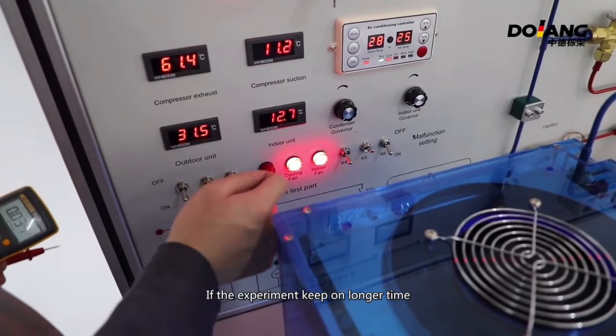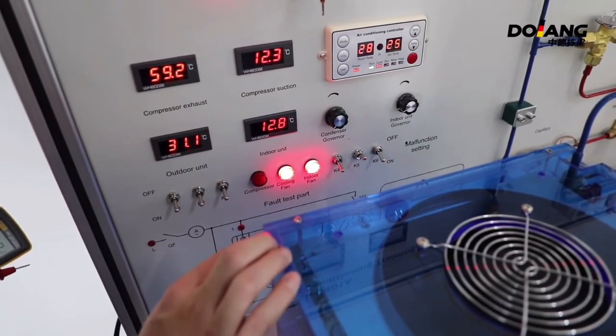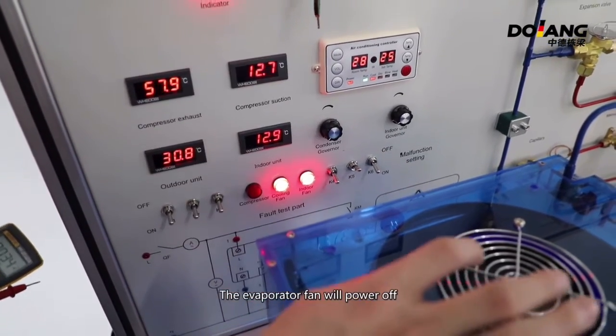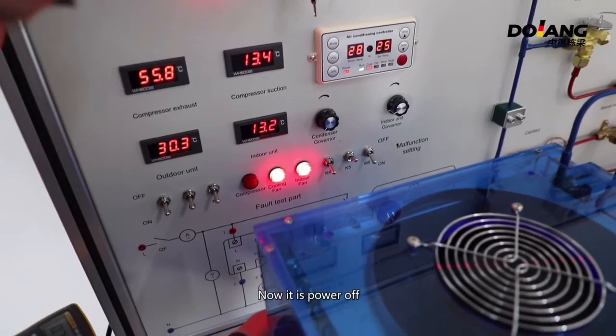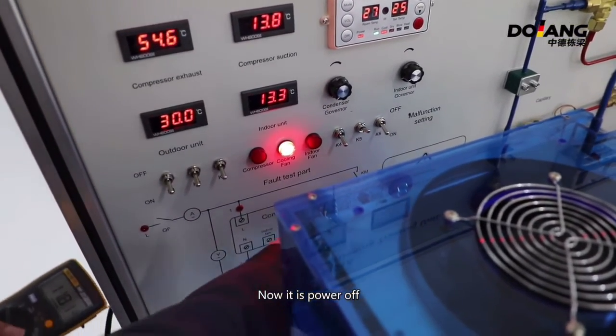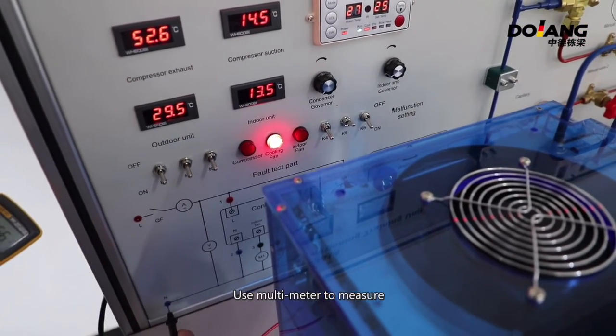If the experiment keeps on for a longer time and you don't turn on K5, the evaporator fan will power off. Now it's powered off. Use a multimeter to measure it. It means it's a compressor fault.